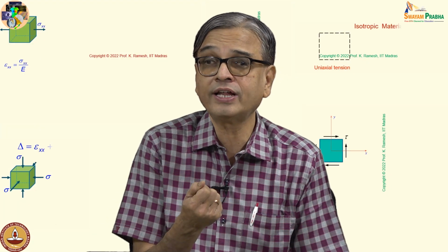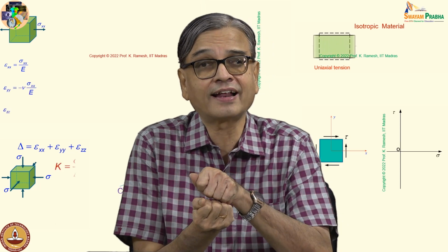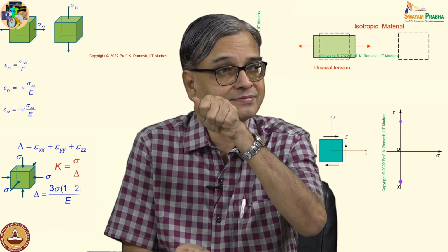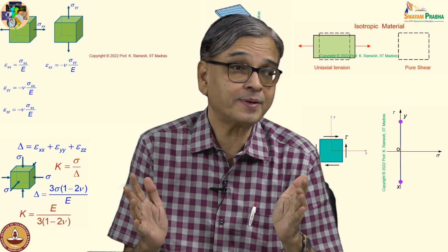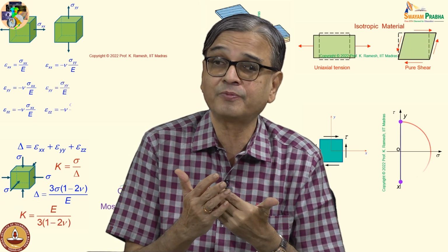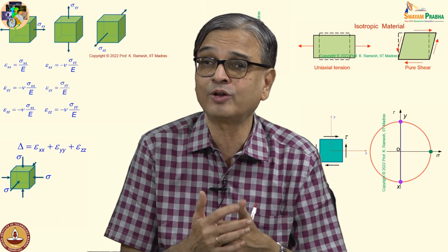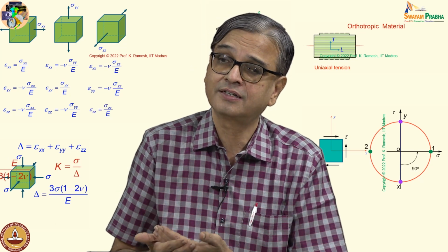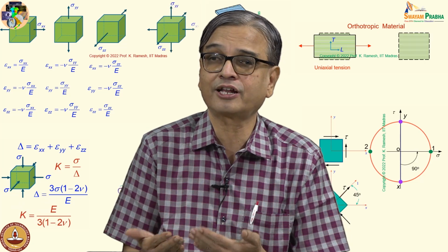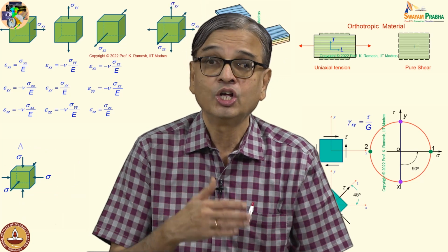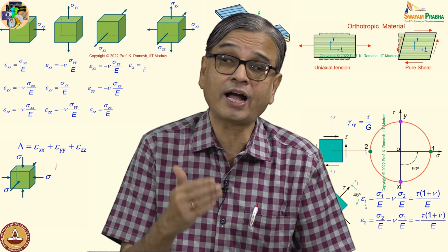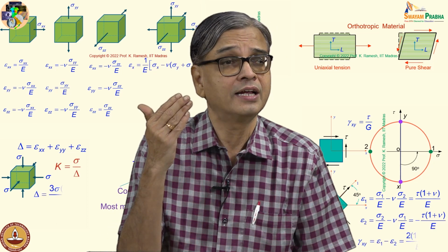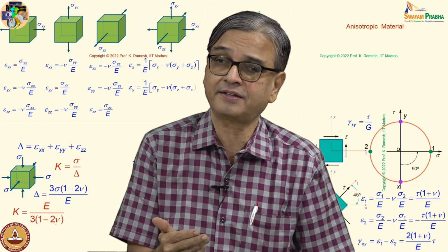And you should also understand that this is plotted for the bulk material. And how is the loading done? The loading is gradually applied, and it is done at room temperature. Now we work on extreme environments. We work at very high temperatures as well as very low temperatures, like your cryogenic engine and so on. For those applications, you have to redo the tension test and characterize the material.